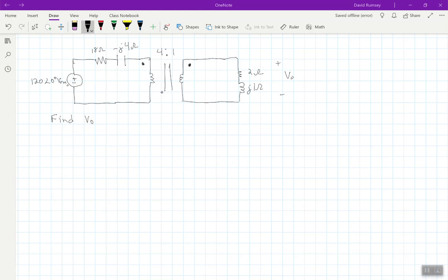Okay, in this example here, we're still given an ideal transformer, and we have turn ratio 4:1, but in this case we have some kind of line impedance and capacitance going on here, and then the load has both a resistor and inductor. And as a side note here, if you tend to have a capacitive load, capacitive line impedance here, we want to have an inductive load.